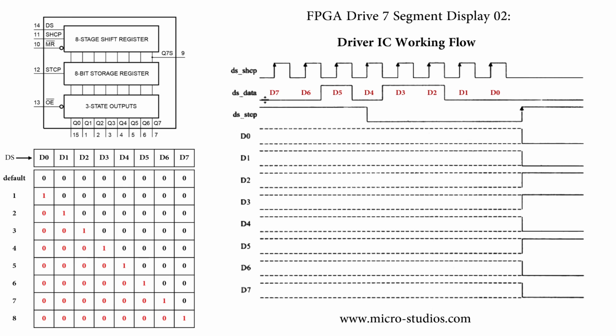Okay, so this pin is data 7 and this pin is data 0. This is the last bit that came into the shift register. Okay, so for this logic IC, understand this function diagram and this waveform,